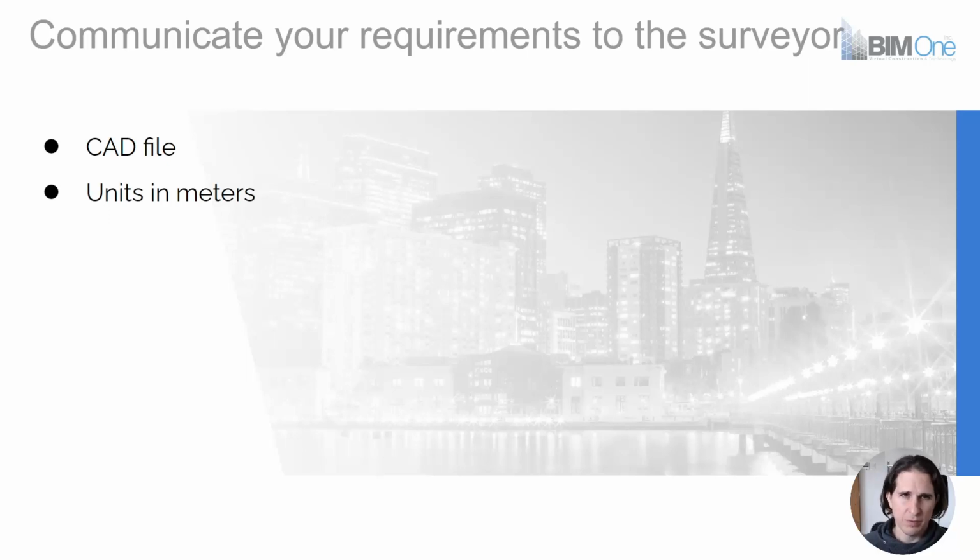Usually they use meters, but it's always good to ask beforehand. Is the project georeferenced with a single or multiple UCS? If you have multiple UCS, beware that when you insert that in Revit, you would have to pick one properly. It's usually better practice to remove the unused UCS, the ones you don't need.